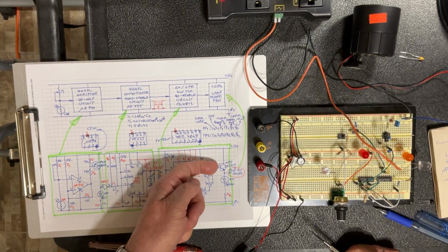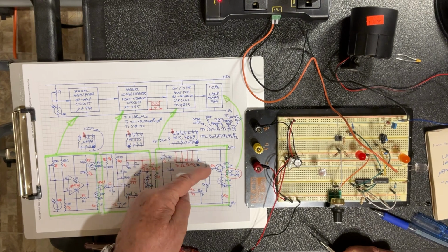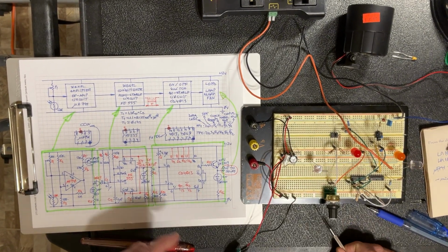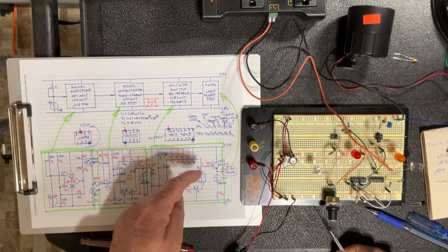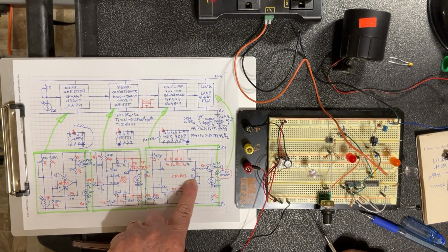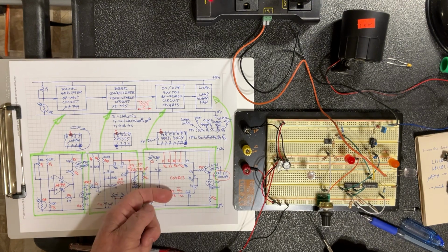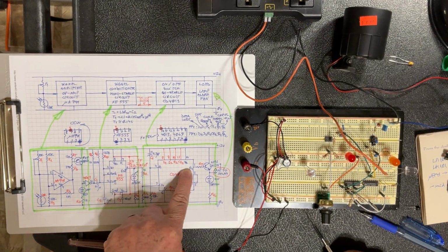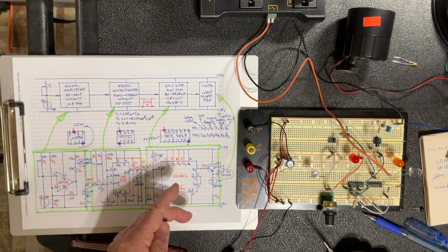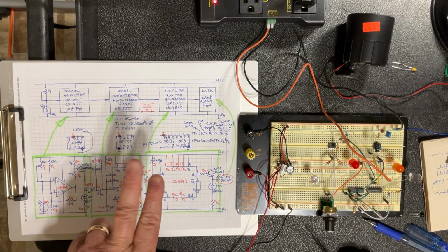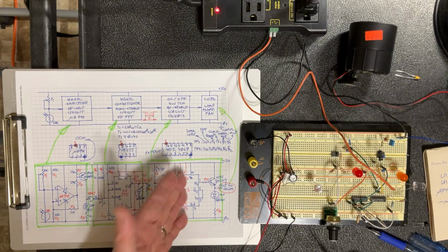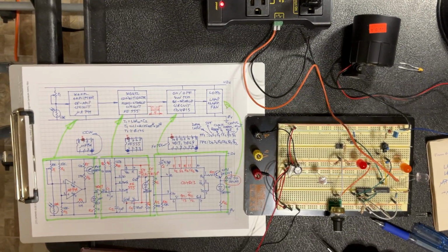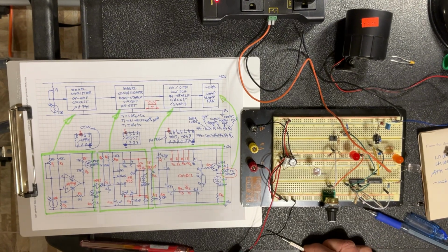But being 0 going to the output is going to put the light off. And then by putting it off, the complementary output is going to be 1. So next time I press the clock input, the 1 is going to go to the normal output and so on. This is why the output is actually flipping like a switch: on, off, on, off. This is how it's working, okay? So very quickly, just to have an idea about how it's working.